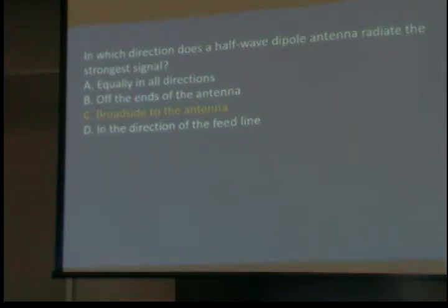When we do this with an antenna, we like to do it with two people. I'm not looking at where I'm facing, but we put somebody off the end of the antenna, and they shoot a compass line over the antenna when we've got the point. And then we add 90 degrees, because this is more accurate than this.